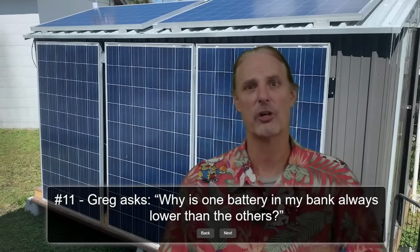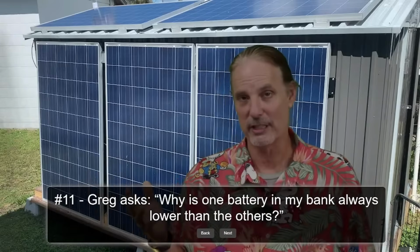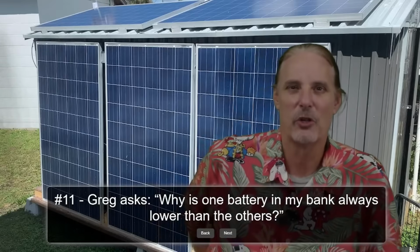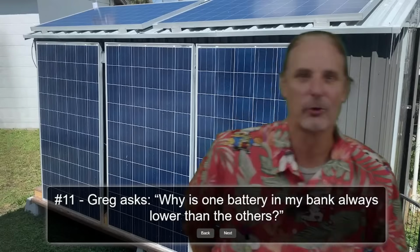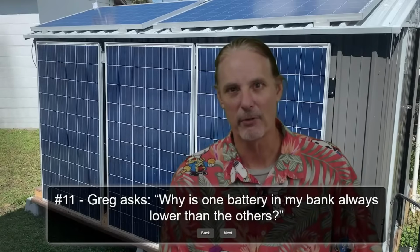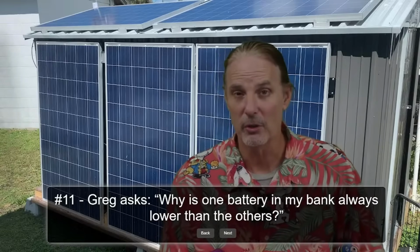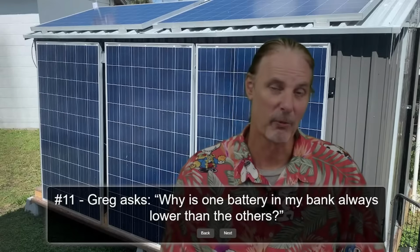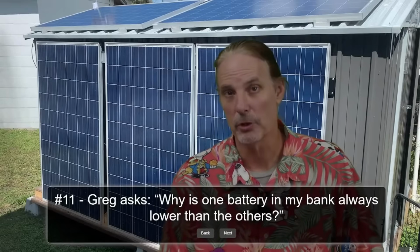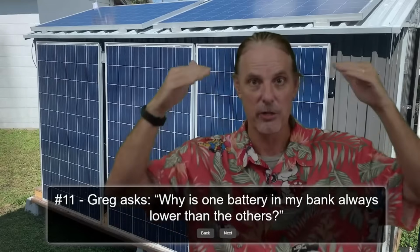Thus, the reason for the state of charge being wrong, and the subject matter of the whole day's live stream, is that the state of charge can still be inaccurate because there are so many variables and so many different compounds and chemicals and electrical devices and things within the mix of all of this that there simply is no way to make it perfectly matched all the way up and down. You can get close, and I've gotten very close in some batteries, but you can't really get 100% all the time. You have to top balance or bottom balance in order to make the difference up and to get some kind of reset on a regular basis.